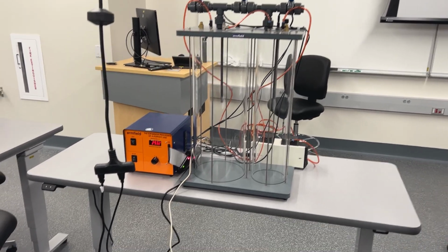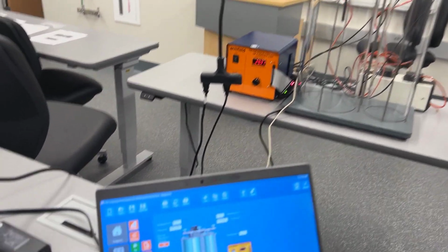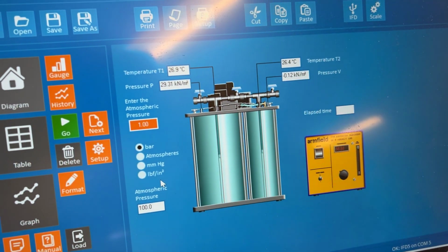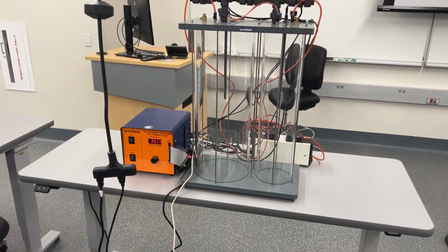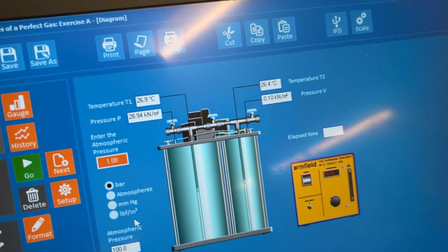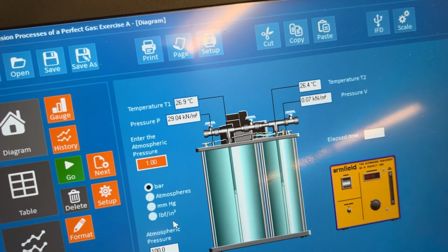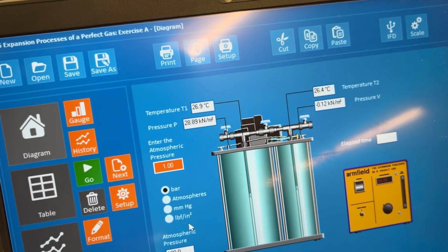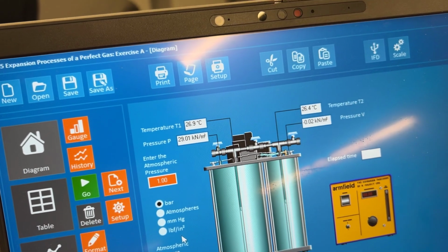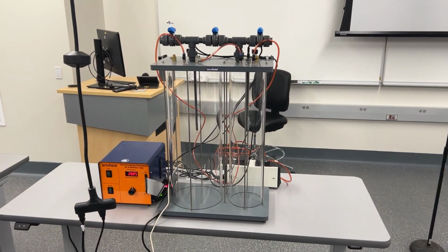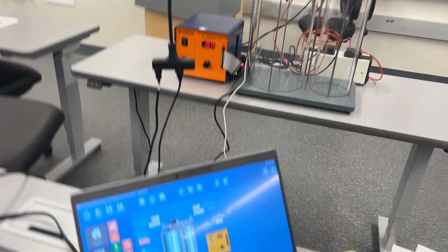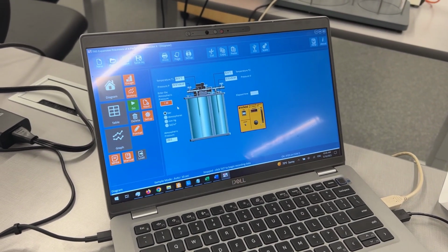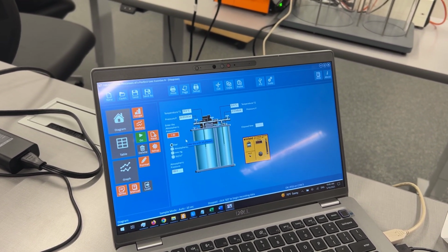Of course, this temperature will decay, through heat transfer to the surroundings. And the pressure decreases as well, because the temperature is getting down, it's cooling, and the pressure just follows. So why is the pressure decreasing? Are the valves not fully closed? No, it's just cooling, that's all. Here it asks you for the atmospheric pressure, and I just set it to 1 atmosphere, 1 bar.